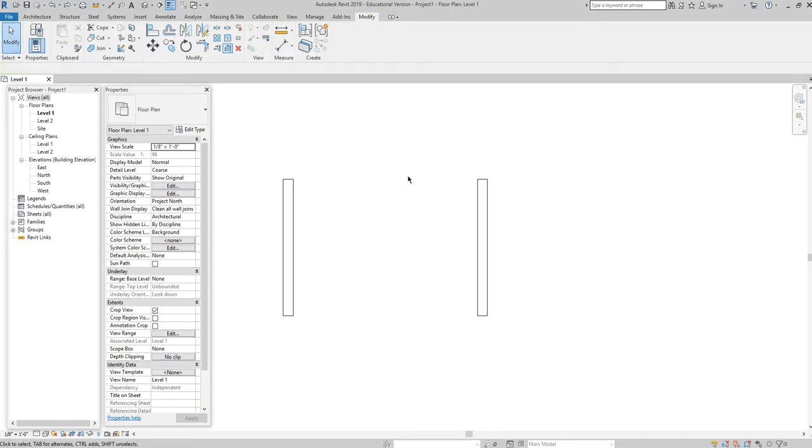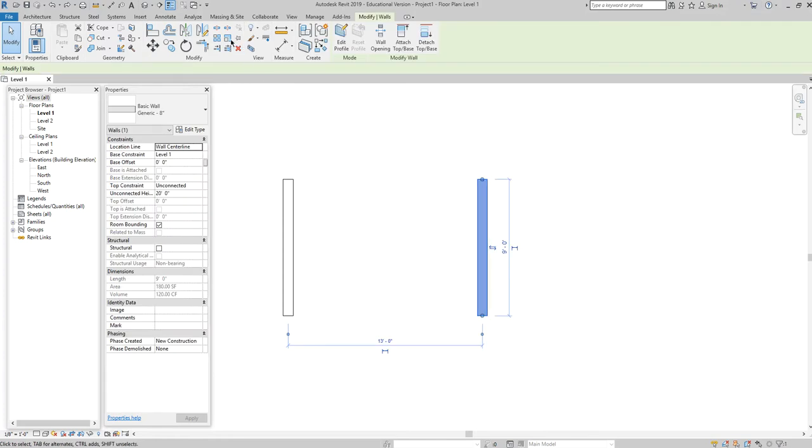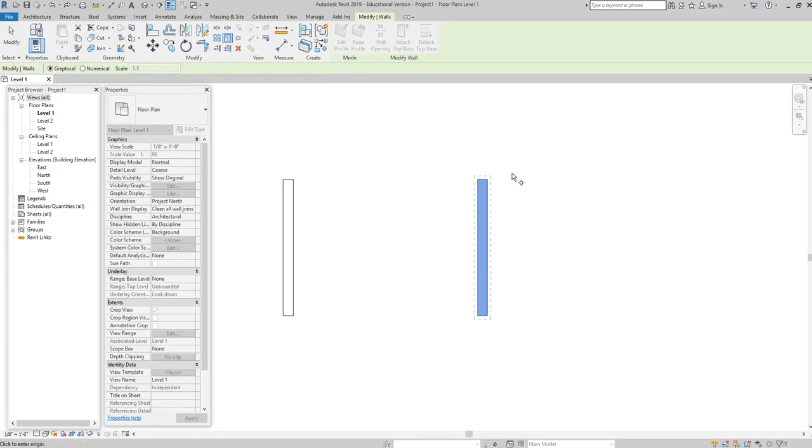I'm going to scale this again, click, scale. Oh, where am I? Click, okay, there we go. Click once, click a second time to specify the length. Now I'm going to keep moving, or I could shrink it, I could make it smaller. But I'm going to keep moving and say I want it to be 15 foot, enter.